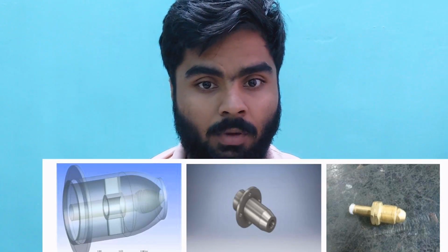A turbine that is driven by a high velocity jet of water or steam from a nozzle directed onto vanes or buckets attached to a wheel. The resulting impulse, as described by Newton's second law of motion, spins the turbine and removes kinetic energy from the fluid flow. Before reaching the turbine, the fluid pressure head is changed to a velocity head by accelerating the fluid through a nozzle. This preparation of the fluid jet means that no pressure casement is needed around an impulse turbine. Okay, so this is the photograph for the complete project diagram. They have discussed this in their research paper.